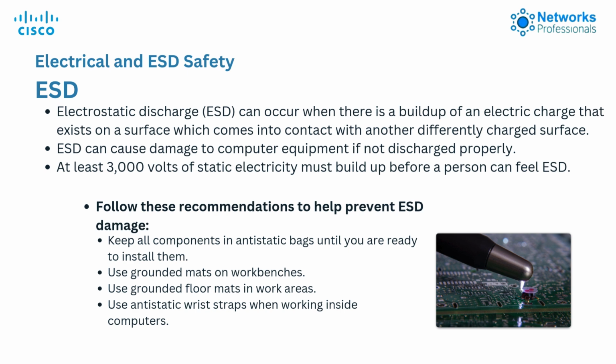Keep all components in anti-static bags until you are ready to install them. Use grounded mats on workbenches. Use grounded floor mats in work areas. Use anti-static wrist straps when working inside computers.